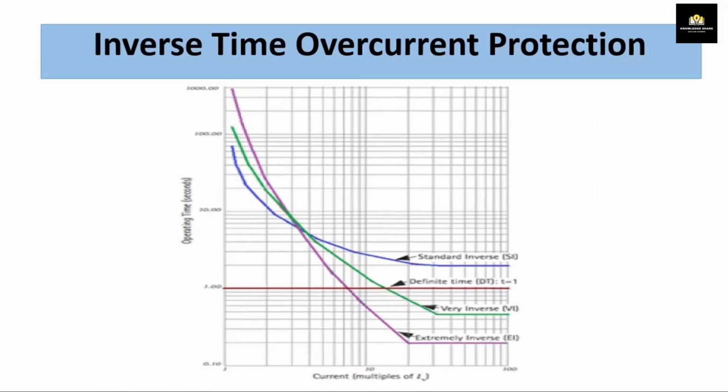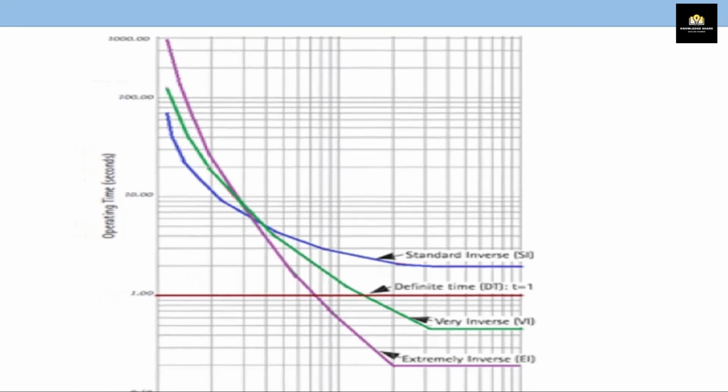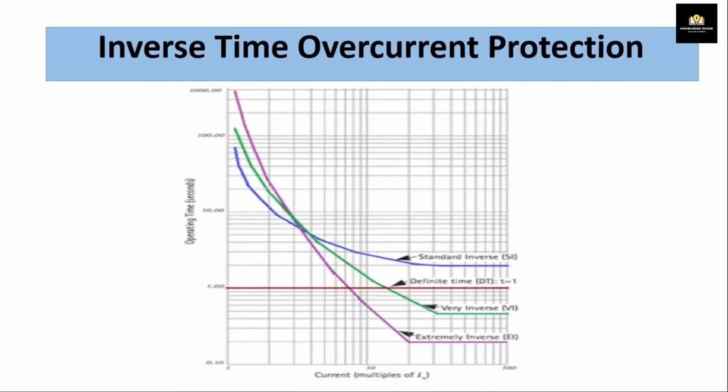With extremely inverse characteristics, the operating time is approximately inversely proportional to the square of the applied current. This makes it suitable for protection of distribution feeder circuits in which the feeder is subjected to peak currents on switching in, as would be the case on a power circuit supplying refrigerators, pumps, water heaters, and so on, which remain connected even after a prolonged interruption of supply.